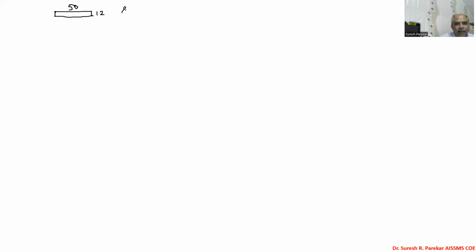So we have r minimum equal to root of I by A, and I is B T cube by 12, divided by B into T. So this is not T by 2, we have this as B into T. So B, B cancel, T becomes T square, and 12 will be there.